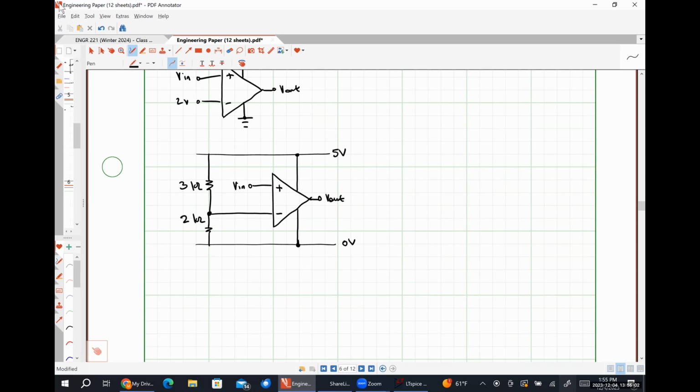So to go from a Y to a delta, because all of the resistors are equal, we'll multiply by 3. So that means we're going to have 30, 30, and a 30. This 30 and this 10 are in parallel, right? So over here, 30 times 10 is going to be 300 over 40.